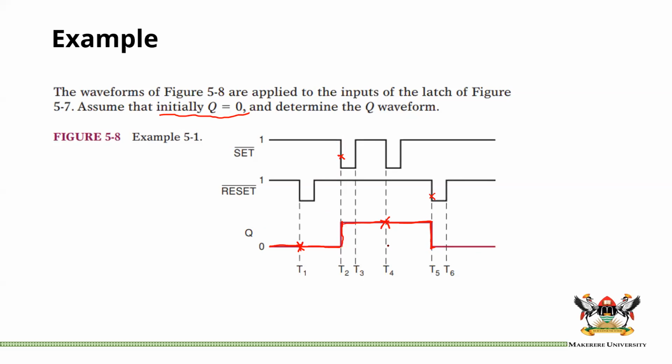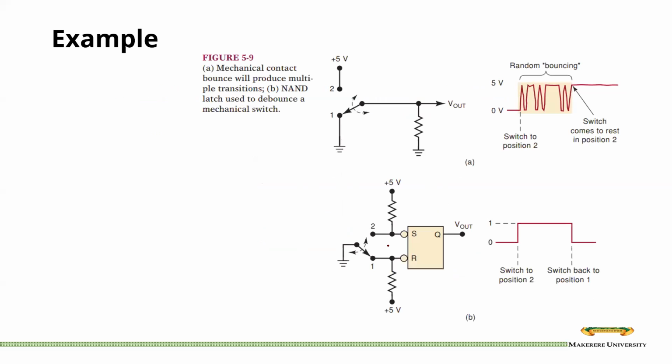So then we looked at the bouncing, the mechanical bounce, or the contact bounce phenomenon, where you produce these sort of signals as the switch is trying to actually settle down on the contact. The terminals are settling down to remain in contact with each other. You get those signals, and in these small circuits, those signals can actually bring problems.